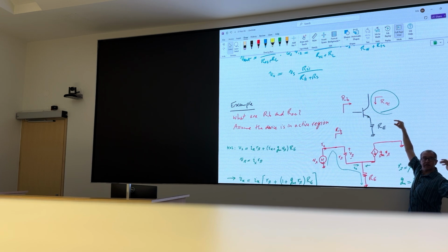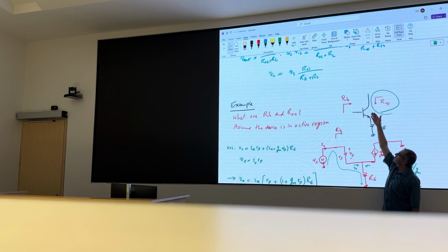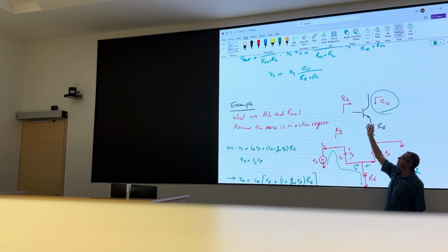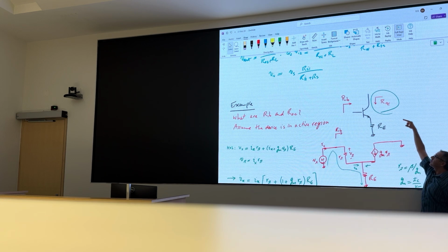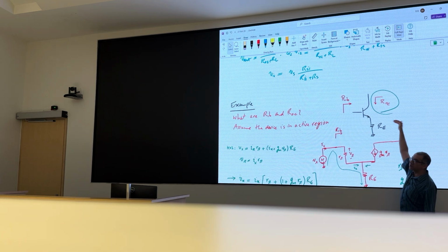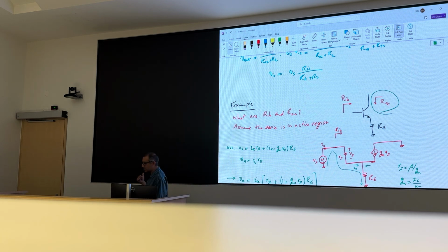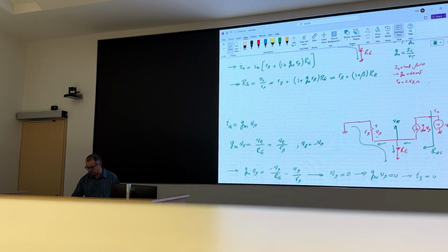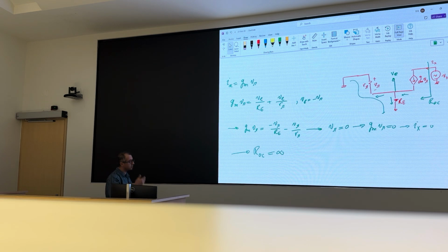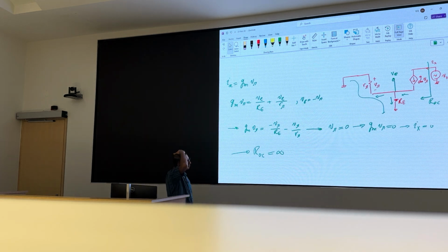Or, yet another way: the current source is a function of some other voltage somewhere else. If you play with the voltage across it, V pi is not changing. So for all those reasons, you do not expect Ix to respond to changes in Vx. But you can also do the small signal analysis and show that it's accurate.